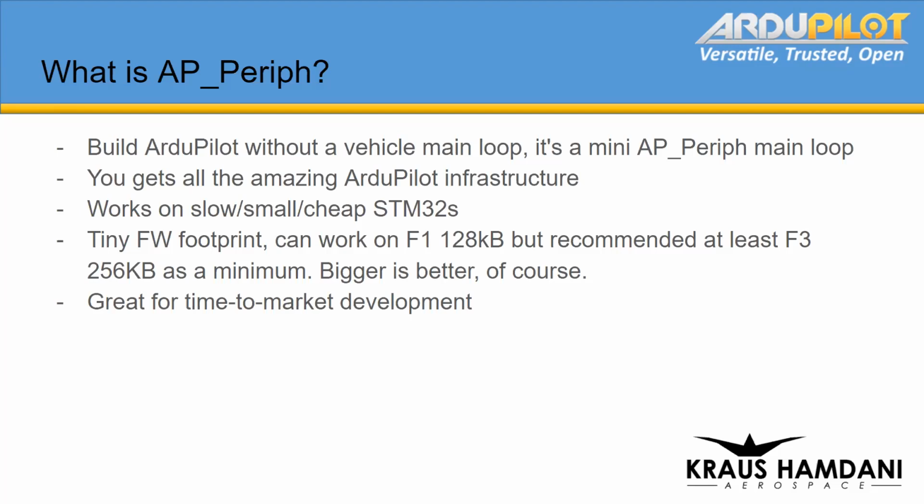There's a few products out there that use an F103, STM32 F103. And it can build for that, but you're really going to have to finagle it a little bit and trim things down. But basically, you want to start with at least 256K, and that runs a few features comfortably, no problem. But I'd actually recommend doing something like an F4 with 256K or higher, just to future-proof yourself. But if you're making a given hardware for just a certain task, you can get by with 256.